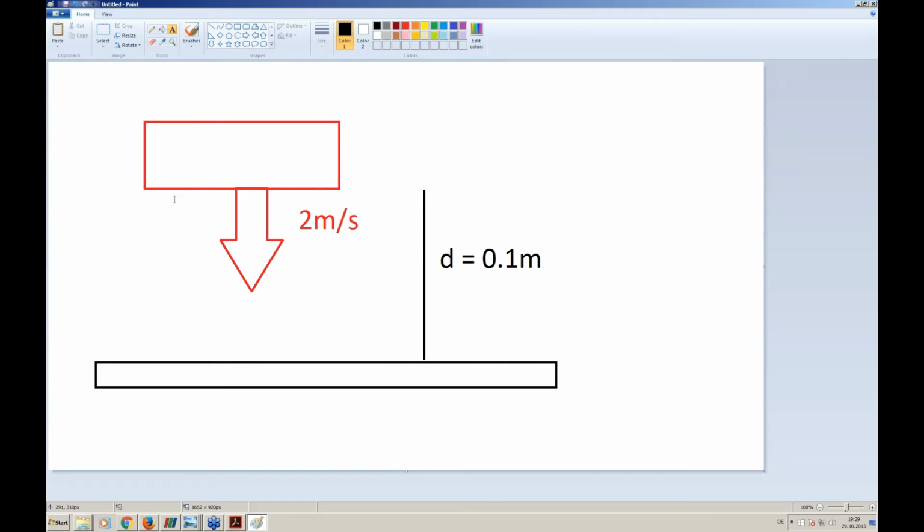And this is again similar to the mesh, because you only need a fine mesh where you have a change, a gradient. Until the first face of the drone touches the floor, there will be no real change of quantities on the drone. Stress, etc., will not really change. Therefore, we can have a very, very coarse time discretization, very large time steps until it hits the wall. And if we want to think economically, the best would be to have a big time step just before the moment it hits, and then have a small time step to really resolve all dynamical changes.